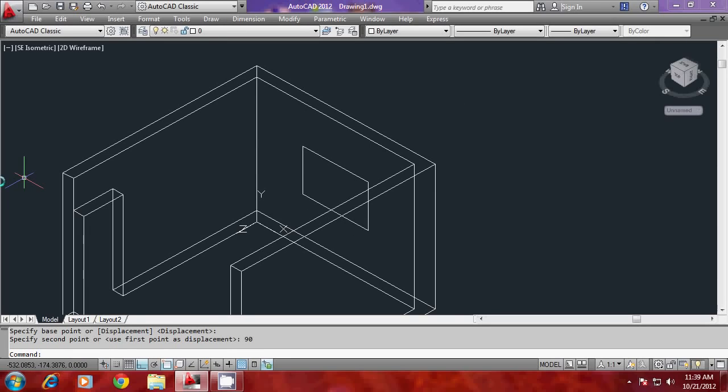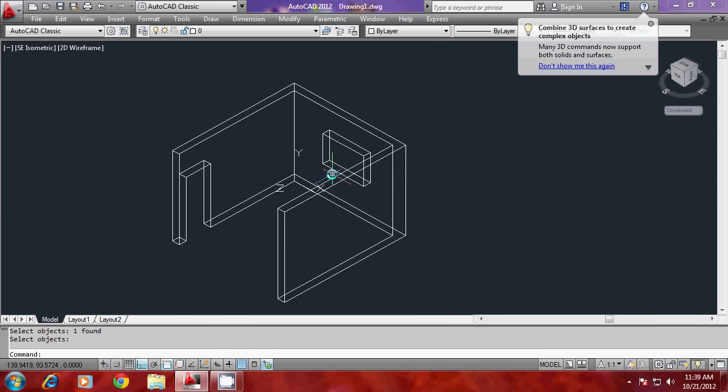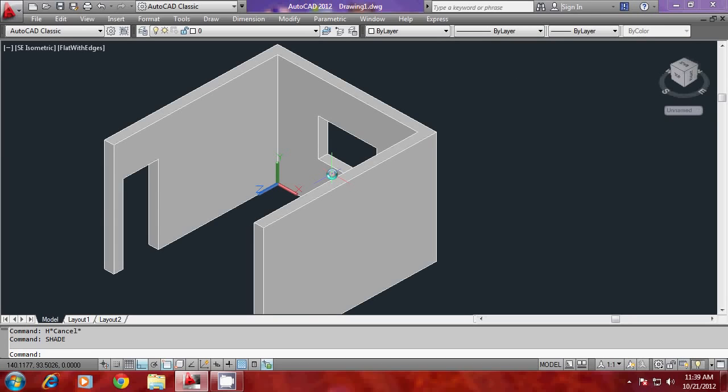So it has matched with the lintel. Now I'll just give extrude to extrude this profile, and I'll give a height of -24, which is the thickness of the wall. Now I'll go to subtract, and from here I'll subtract this solid. So this is the cutout for the window. You can just give a shade and you can experience the shaded representation. Okay, now you can just undo.